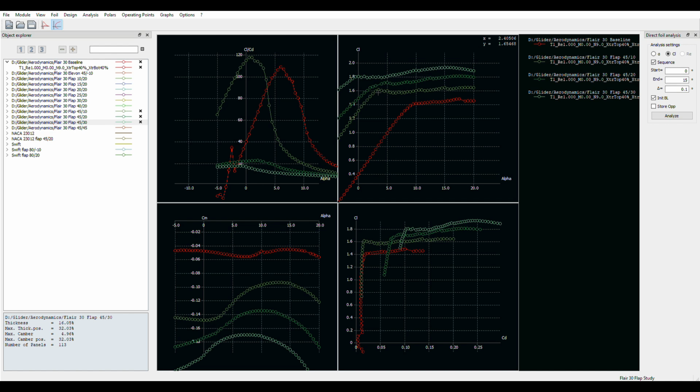slip it? No, it's a stinking flying wing. There is no side slip. There's no way to create drag by flying sideways. All you can do is dump more flap to try to get it on the ground. And in this case, that succeeds. If you dump more flap here, you're going to get yourself on the ground in about 3 seconds, going vertical, straight down. And that's because of where the control surfaces are hinged.